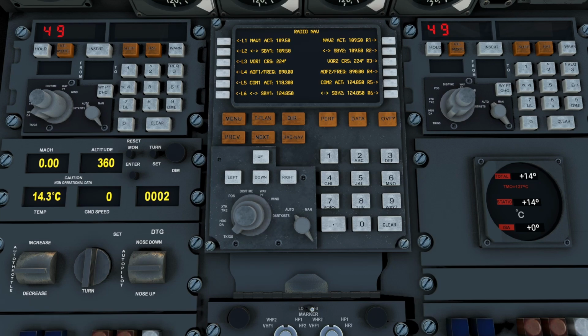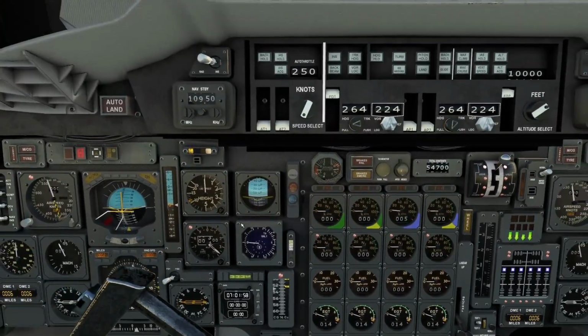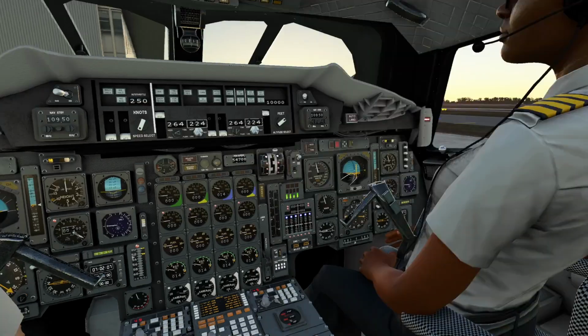With this, we are ready to start our engines. That's a view that you don't really need that often. There are the start switches of the engines, which have to be started in a particular order. You start with engine number 3, you put start, and you can check if the engine numbers are coming up either on the front pedestal but also in the engineer's view.